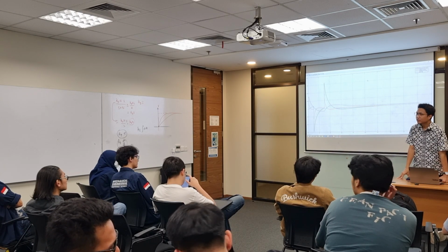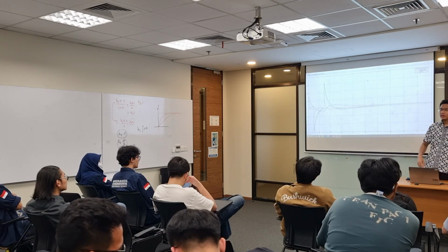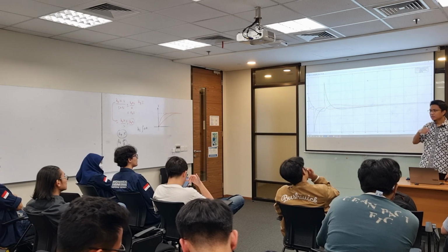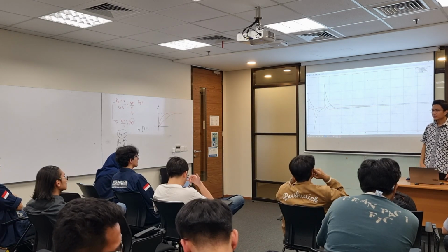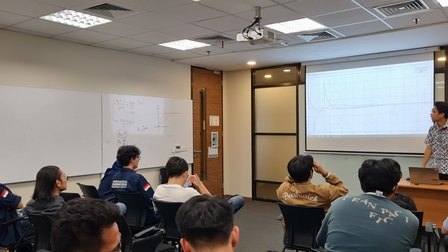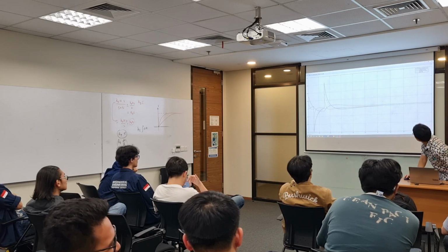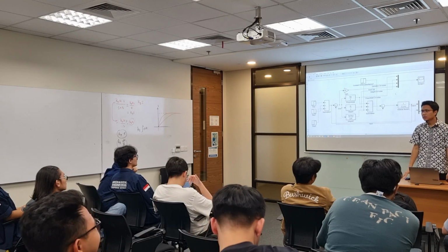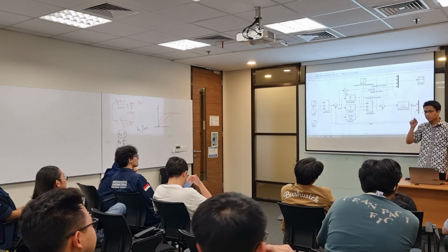It's based on your reference. If you have oscillating input or randomly changing input, then derivative control will help a lot. And sometimes when that's the case, you don't need the integral control. You just need PD control.